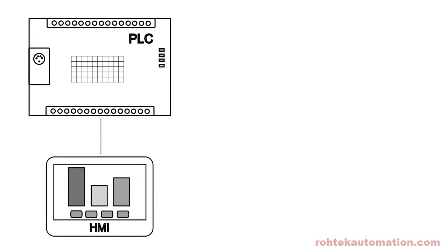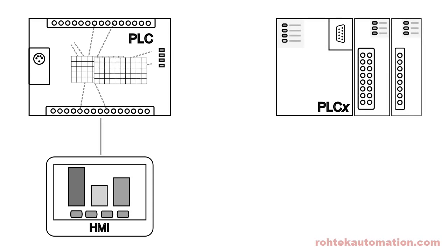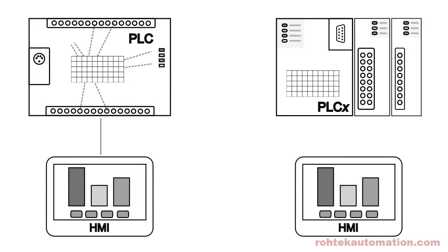Finally, the approach we're advocating here will make your designs more portable, which is to say reusable. This comes into play if you want to reuse your code with new hardware. Using a well-designed interface between the HMI and PLC, as we've been discussing, decouples to some degree the PLC and HMI configurations, allowing a more standardized approach that is less dependent on the peculiarities of the particular hardware, making it easier to upgrade to new models or brands, as is often required by cost, changing company policies, or obsolescence.